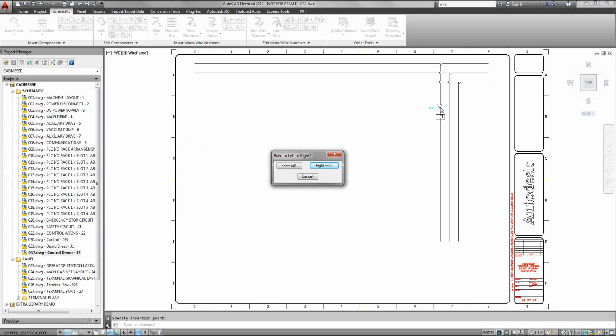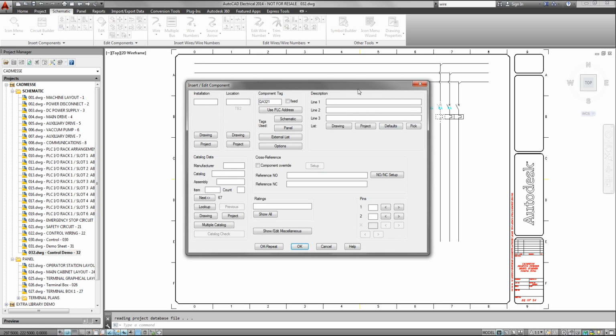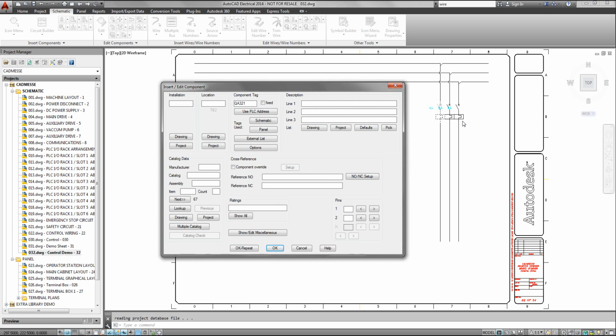the wire spacing, as we've seen, is variable. So how it works is it's called parametric, and it looks for the wire gap, looks for the next wire and places the component on that wire. So the next thing the software asks me to do is which way do I want to search for the next wire, and we obviously want to go towards the right. So I hit right and it places all 3 symbols in on the 3-bus wire there.